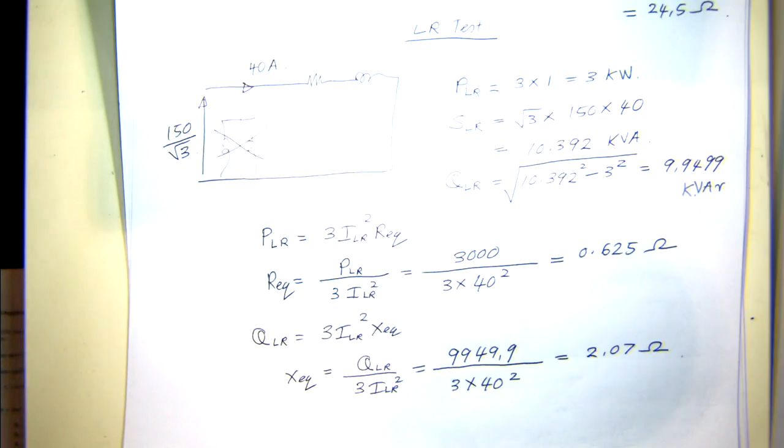But let's say it's a train or some other application where you want to brake the system, let's say stop it really fast, then if it's a DC motor, you would actually apply a negative voltage and then work it as a generator. Similar concept can be applied to induction machines as well.